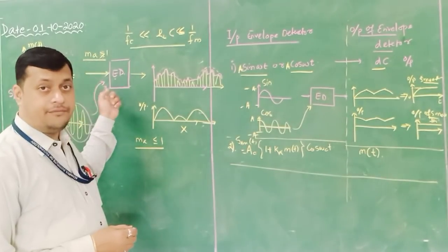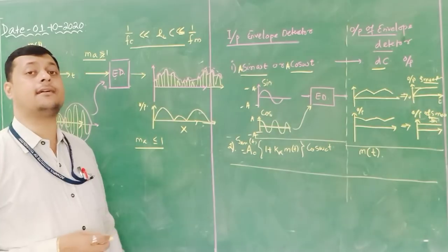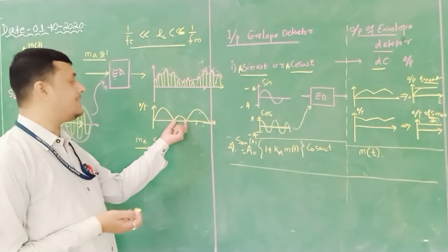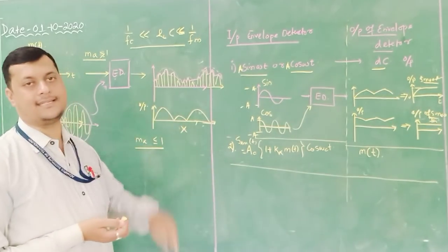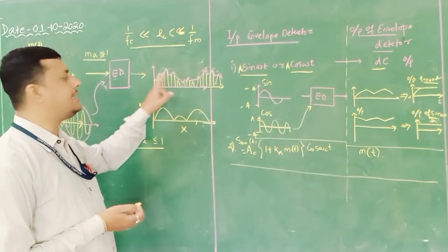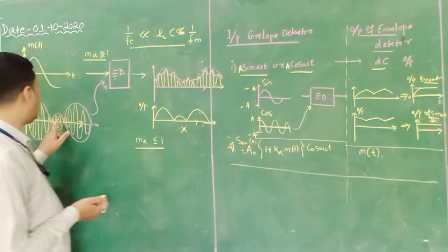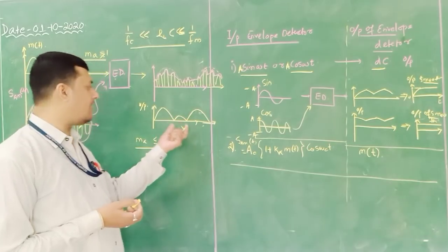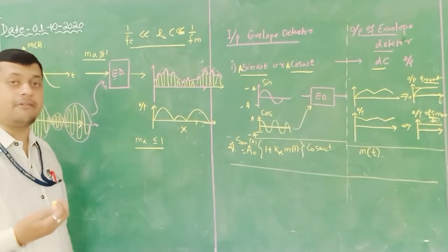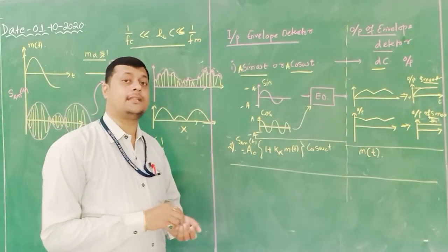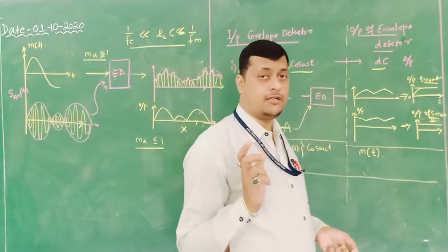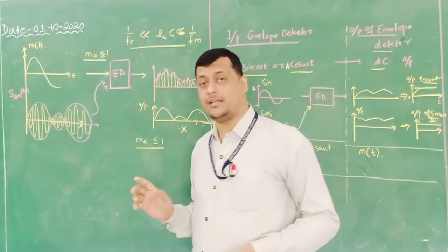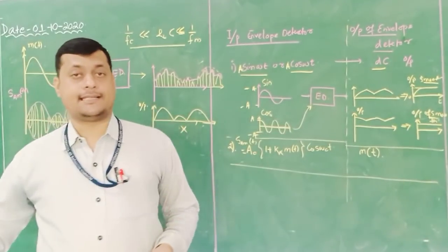But when we transmit the signal with over modulation, the reconstruction of the modulating signal is very difficult. Different sorts of outputs will come, a distortion will come. Here it is not my message signal; a distorted component is available in the received modulated signal. Due to this envelope distortion, we lose the message signal. We get some information, but it is not the same as what we transmitted. So what is the principle behind this envelope detector? It performs well for the under modulation case as well as the critical modulation case, not for the over modulation case. So in practice we avoid over modulated signal transmission.